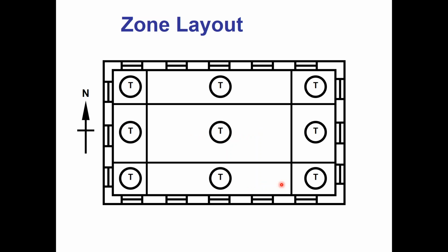Well, here's what we need to do at a minimum to do it right. Now, doing it and doing it right are going to be two different things, but this is what we need at a minimum. We need at least one zone, meaning a VAV box and a thermostat, for each unique space that needs different temperature things. So from an exposure standpoint, from a perimeter standpoint of the building, that's going to equate to me having 8 different zones. I'm going to have an east and a west and a north and a south. And then I have the 4 corners that go along with that,